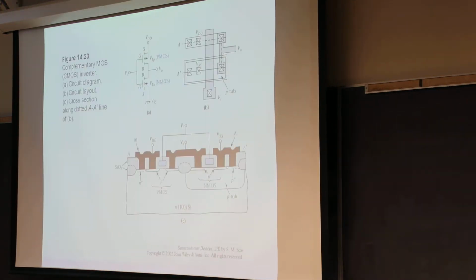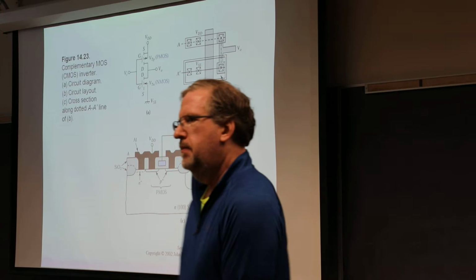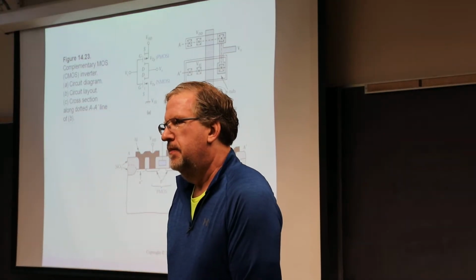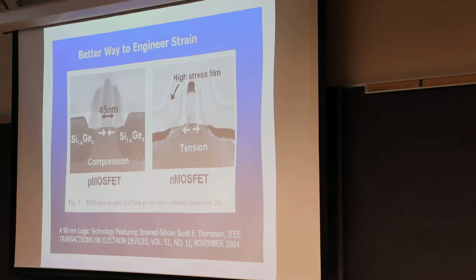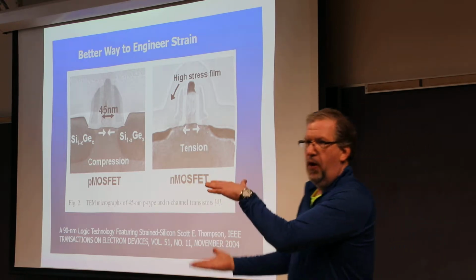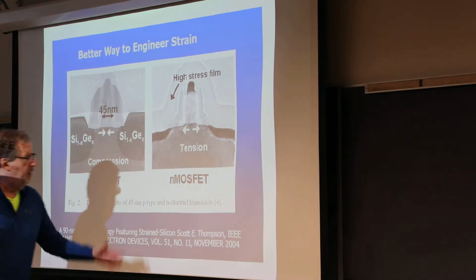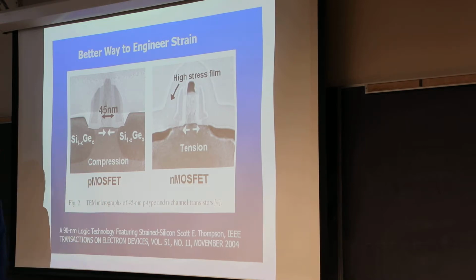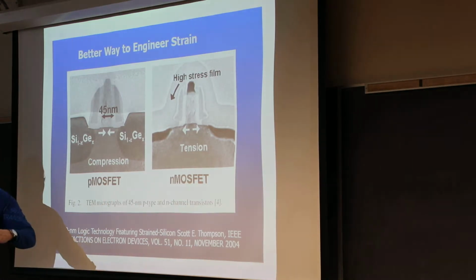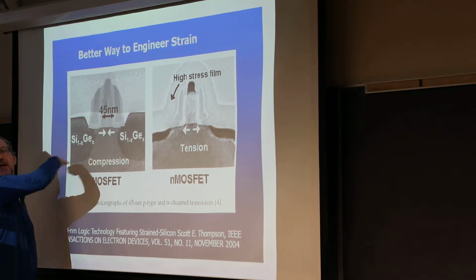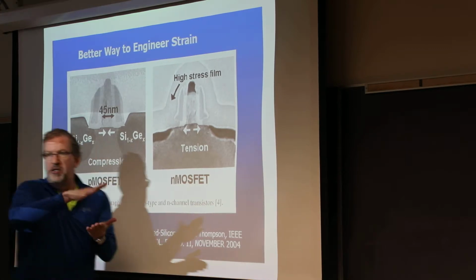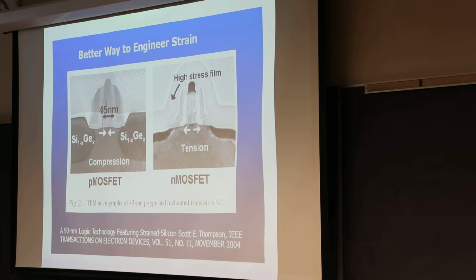So back on the other slide, what was the 100 direction? Is it the substrate? If I bought a bin of wafers and ordered it from the vendor and then started to put it through my Intel factory, those wafers are 100. So this plane would be the 100. The transistors are sitting on top of the 100 plane. That's the dinner plate that you're sitting on.